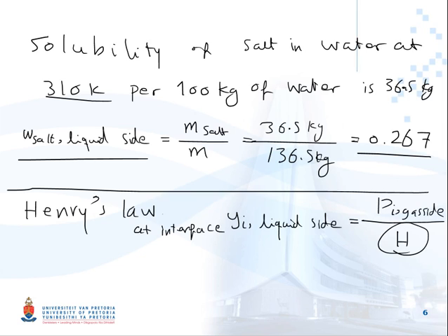But can I use it everywhere? Anytime that I'm dealing with liquid and gas interface, can I go and use Henry's law? No. It's only valid for dilute solutions, not for every single situation that you are facing. So then what are we supposed to do if the solution is not dilute, like ammonia in water? In this case, we use another law.